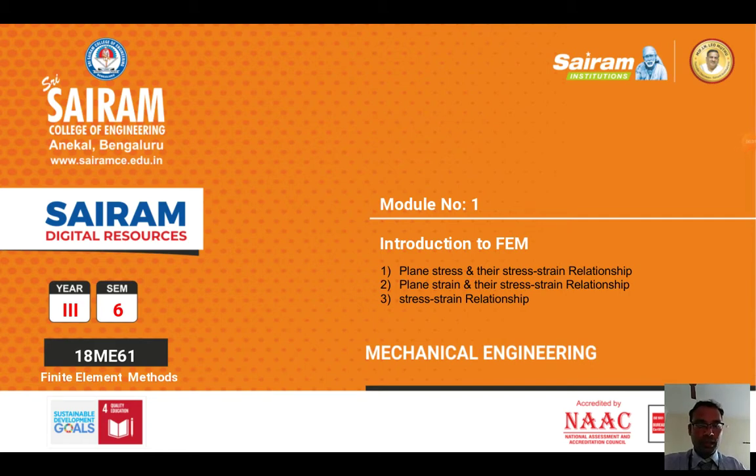So, in this PPT, I'm going to tell you about the concept of plane stress and plane strain, and what the relationship is between stress and strain for both cases. Normally, plane stress is nothing but what? Plane stress is represented by a very thin plate. In the XY direction, the plate is subjected to an in-plane load, along X or maybe Y direction, and no load along the normal to the plane. Such a problem we are going to call a plane stress problem.